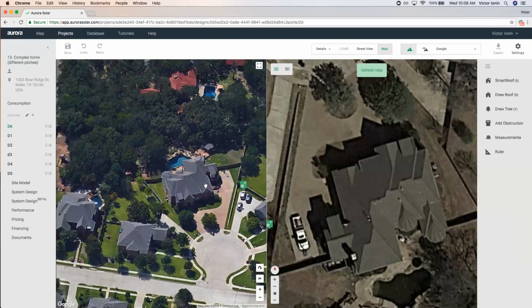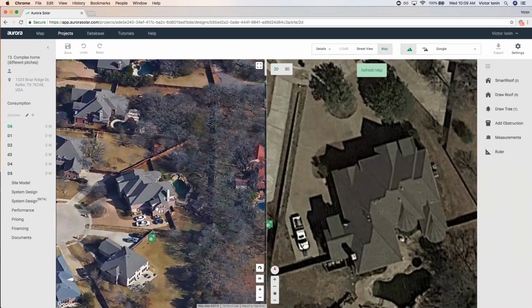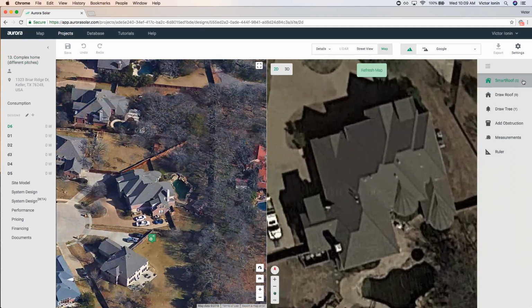You'll notice things like dormers, gable dormers. Ignore those. We'll use the dormer tool to add those in. Now, you might be tempted to use the dormer tool over here. You can. I'm not going to, only because you'll notice one side of the dormer kind of shoots up all the way to the ridge, so it's not really a symmetric dormer. And if you want that kind of feature in there, you don't want to use the dormer tool. So I'll draw that in as a part of my roof drawing. So you'll see, lower levels, dormers.